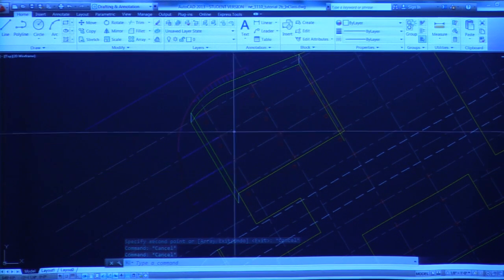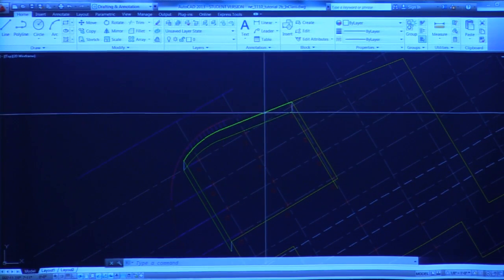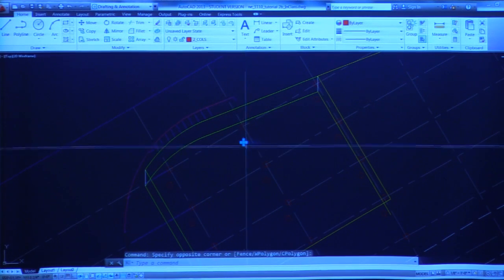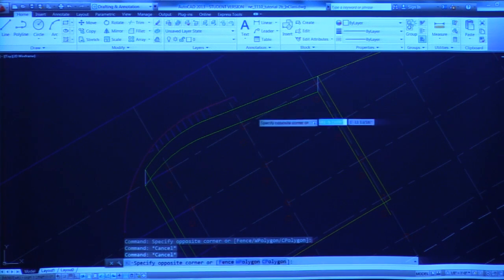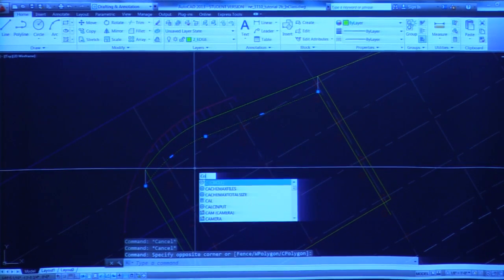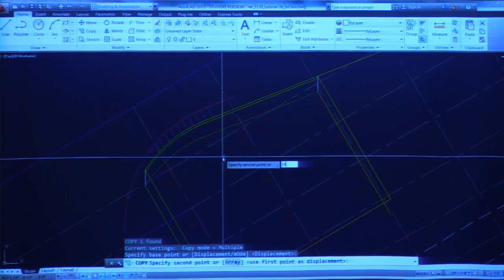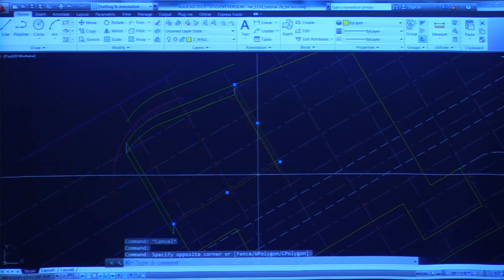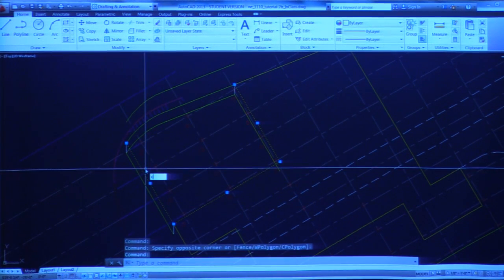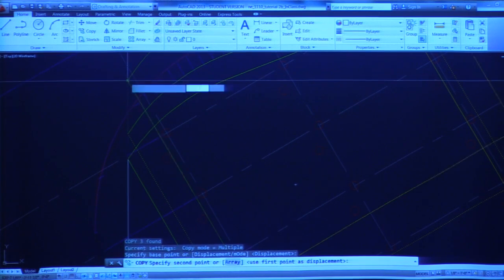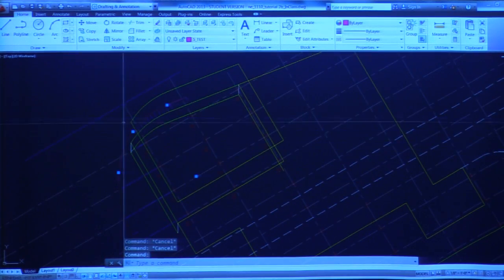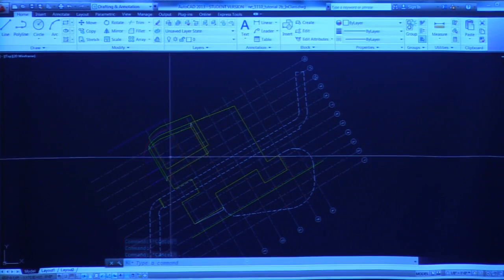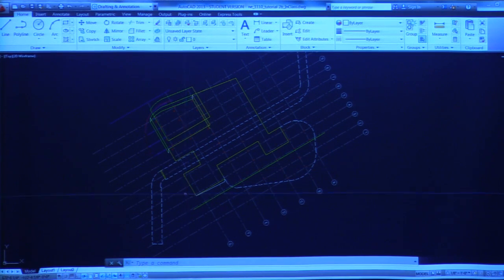And you probably have measurements to the underside of the slab there. I think it's probably around 14 feet or something, so you can go back up from that ground to the underside of the slab. So I'm going to copy that up 14 feet. And that will give me the underside of the slab, and I can copy these guys up there as well. And if I had this drawn correctly, I could finish up that whole lobe. So now you can start to see the 3-dimensional space starting to develop there.